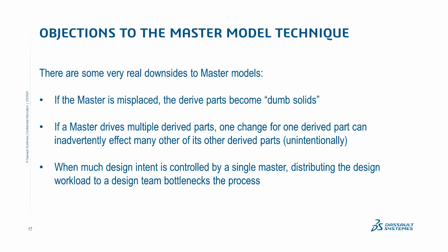If you have a master that's driving multiple parts and you want to make a change for one of those parts, it can be somewhat obscure what it's actually changing in other parts. And you just want to pay attention to that feature in the master and check all the other parts that are coming from that master model to make sure that they aren't unintentionally being changed also.